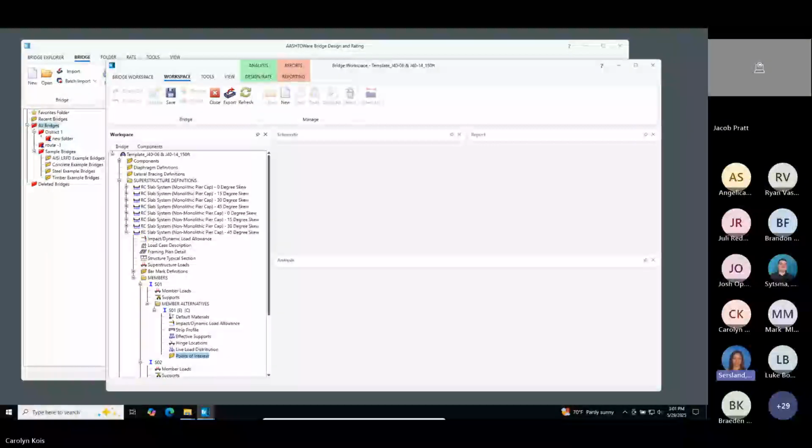Really, whether it's monolithic or non-monolithic, you're going to load rate it the same with that just solid thickness all the way across. So whether it's monolithic or non-monolithic, we got rid of that. We're just going to treat them all the same. Also, like they said, instead of the 12-inch strip, we decided to do the full width of the slab.